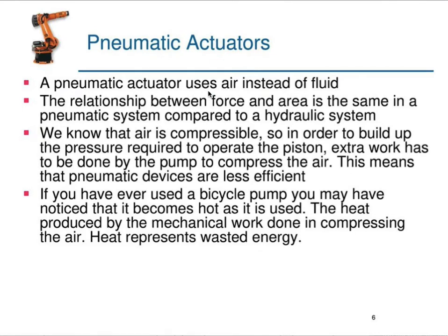A pneumatic actuator uses air instead of fluid. Hydraulic systems use liquids or fluids, and here in pneumatic you use air instead of fluid. So the relation between force and area is the same in a pneumatic system as in a hydraulic system.